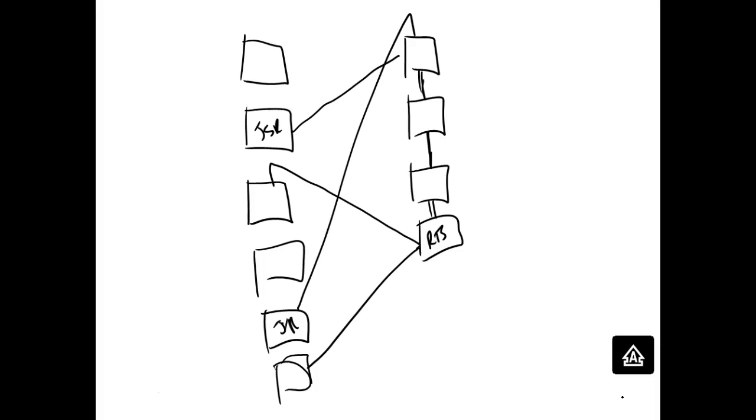Every time you wanted to do the same thing, you wanted to repeat the rung. Of course, these are computers, and computers have been able to do JSRs as long as I've been programming computers. There's always been a jump subroutine. Which means now, instead of me having to repeat all those runs, I can just do them once, and every time I need them, just jump out.